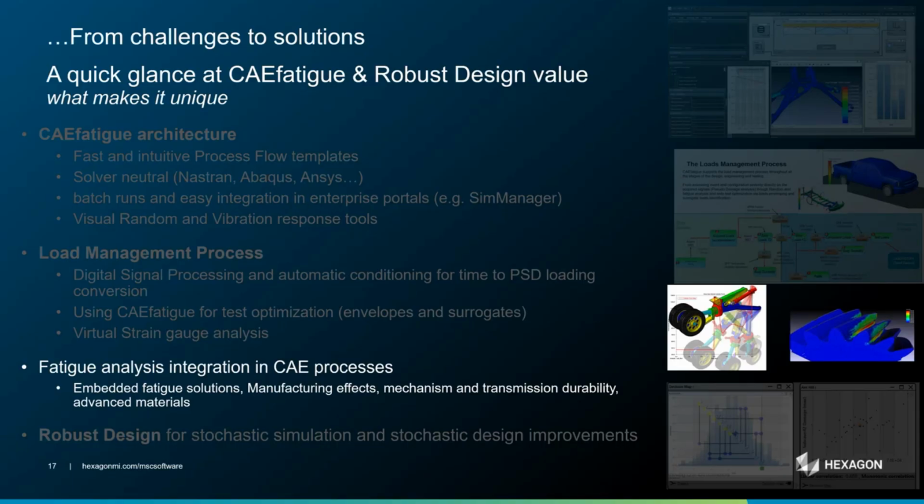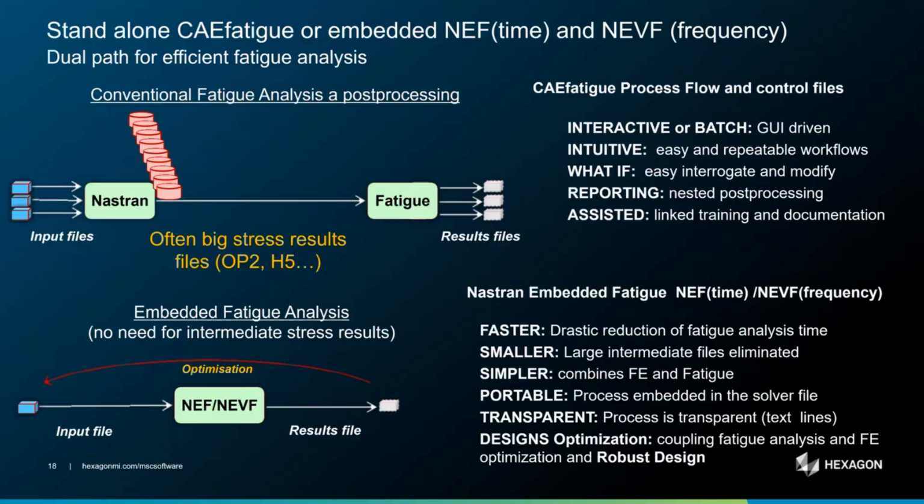Now, I'm going to move into some other examples of tight integration because some of you use other tools. Yeah, I mentioned Nastran input fatigue. This is a simple Nastran embedded fatigue. This is a simple pictorial of what it means to work interactively. So now you first run Nastran, and then you have very big models, multiple subcases, for example, and then you run the fatigue tool on those results, right? So you literally get H5 and multiple H5, or multiple ODB from Abaqus, and multiple RST from ANSYS and so on.